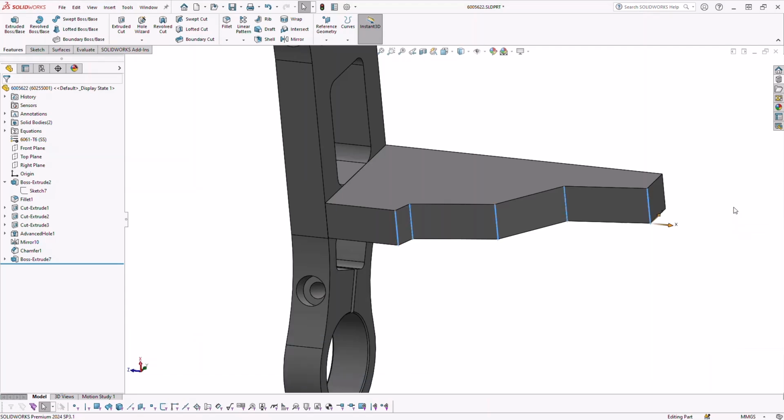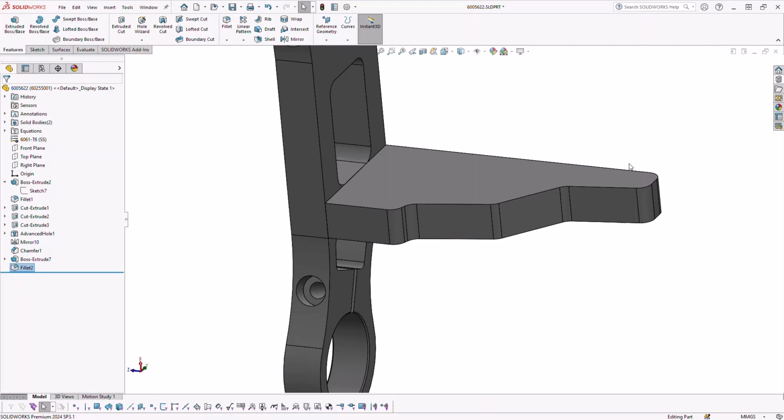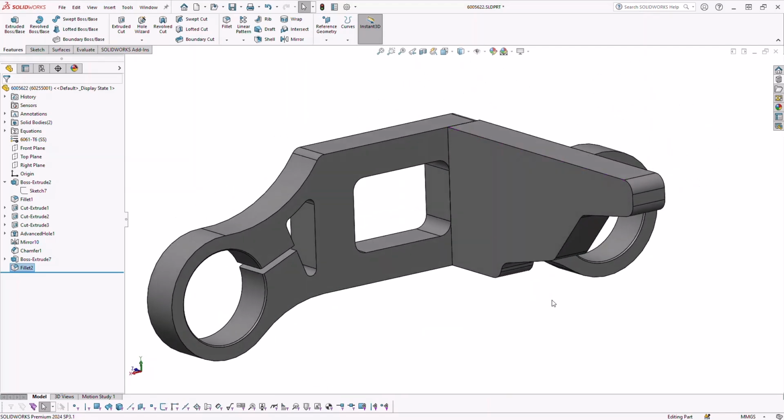This will pick up your previous selection and you can pick up right where you left off. Selecting my final edge and I can start the fillet command. I'll fill in my 5mm value and exit the command. I want to create a cut in this body. I also want to clean up my screen a little bit by hiding the main body.